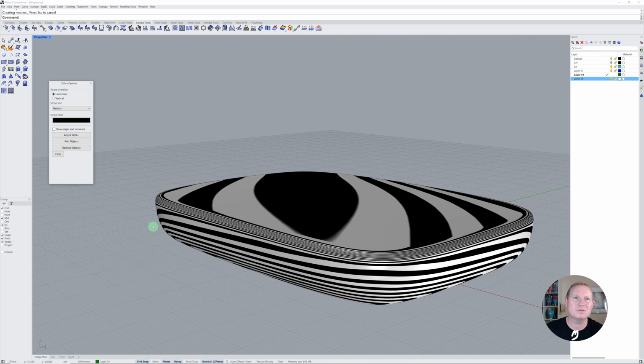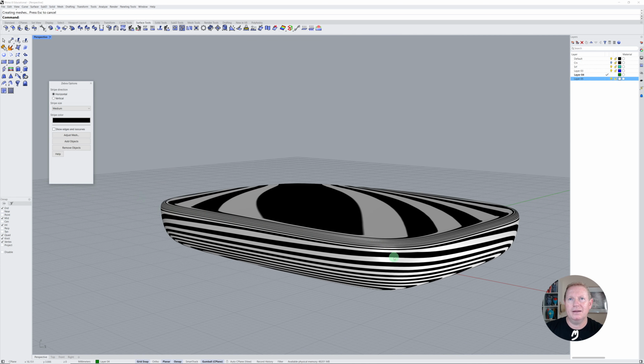What we showed you in class was to create a line, cut the bottom block, offset the curve that we used to create the basic form, and then trim the top surface, and then do a blend surface. Now, there's different ways of doing this. Blend surface lets you go to G4, and I think that the fillet surface was a G2. So if we wanted a G3, then we're better off going with the method that we used in class.